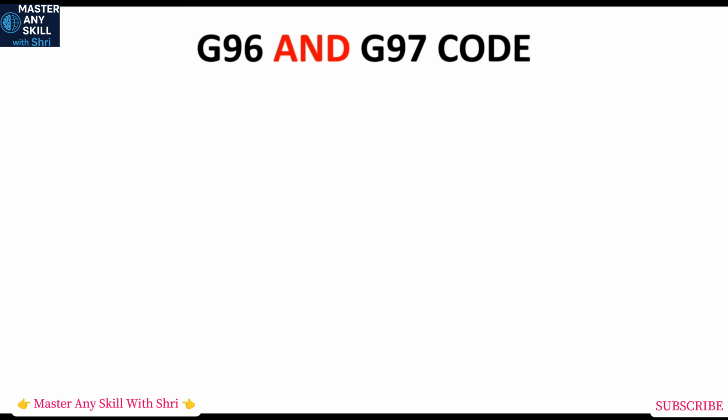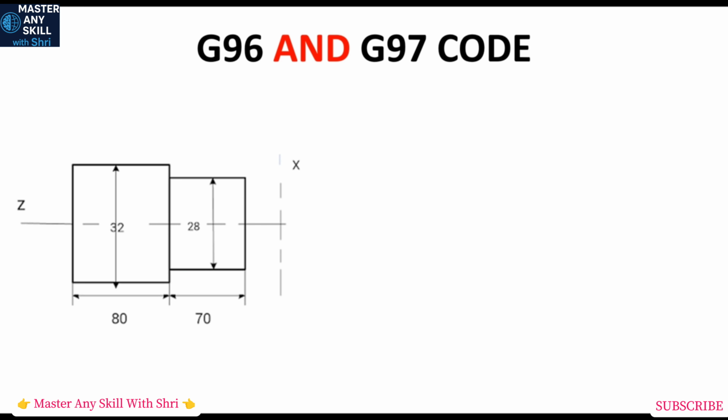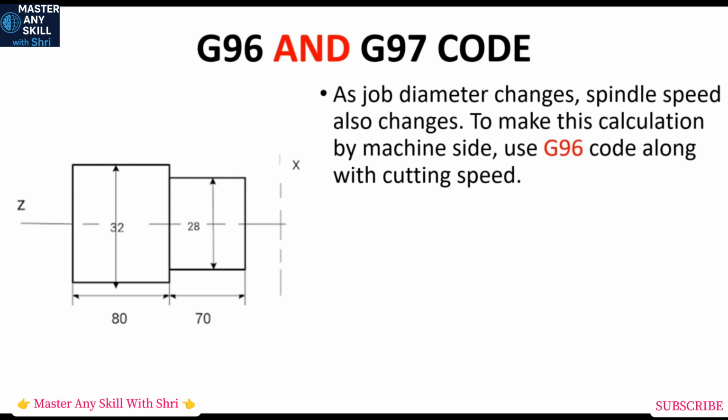As we know, as diameter changes, spindle speed also changes. So if you want all these speed calculations to be done by the CNC itself, then you have to use the G96 code. If the diameter of the job is changing, you have to use G96 code along with cutting speed.